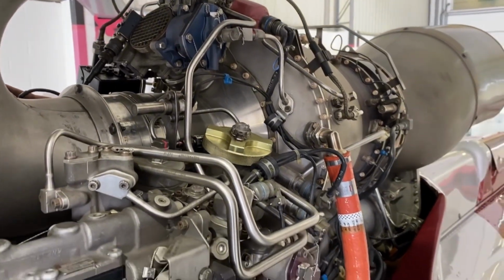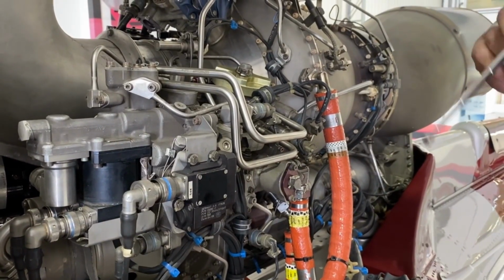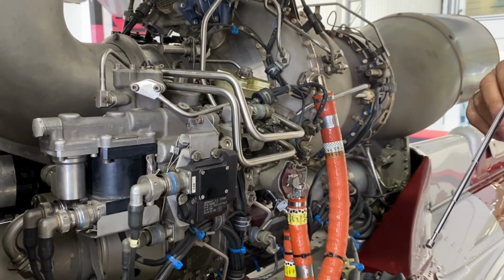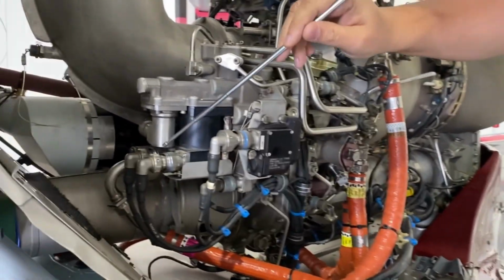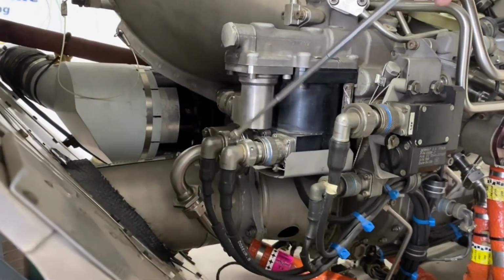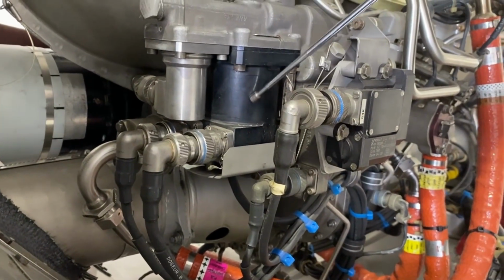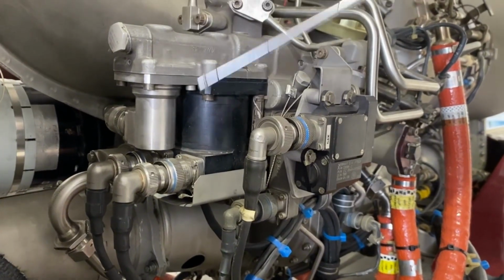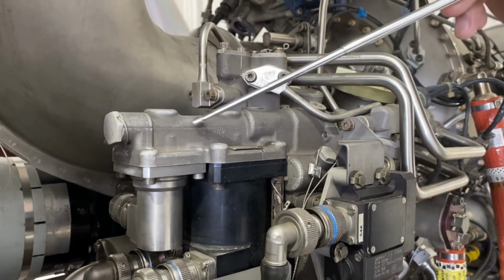The FADEC system, the computer is located in the cargo compartment, and it also receives the P0 pressure there in the cargo compartment, which is the ambient pressure. It controls the signal here, which enters through these 2 plugs, channel A and channel B, of the stepper motor, which is a dual stepper motor. This stepper motor controls a dosing needle that is inside here, inside the fuel control unit.